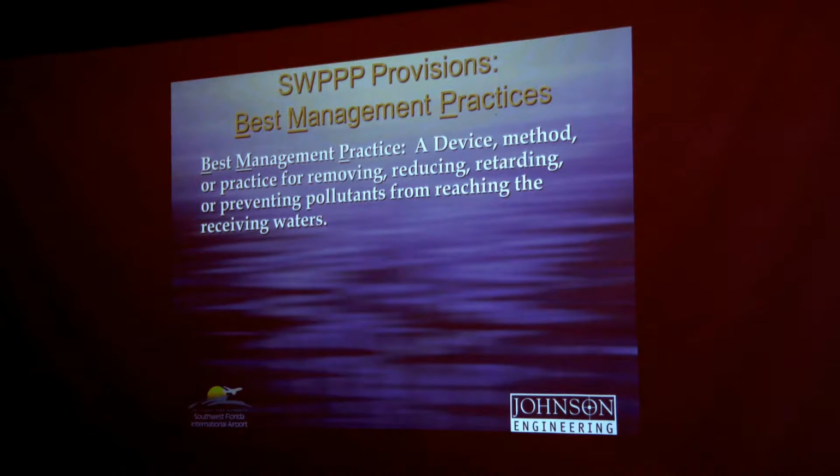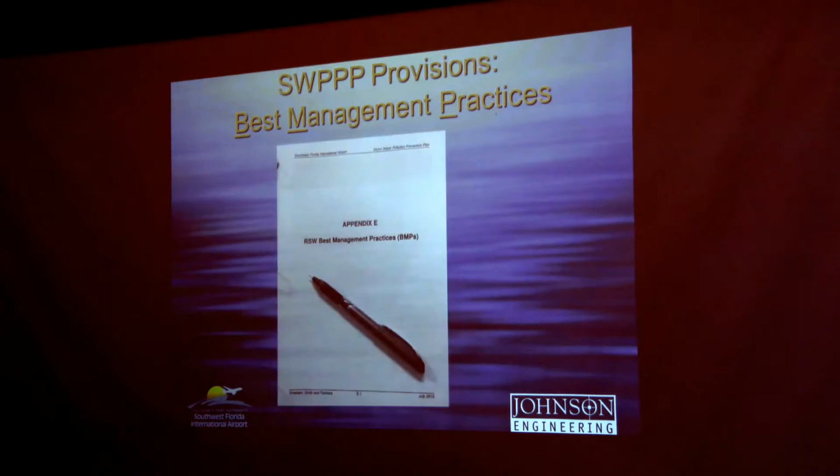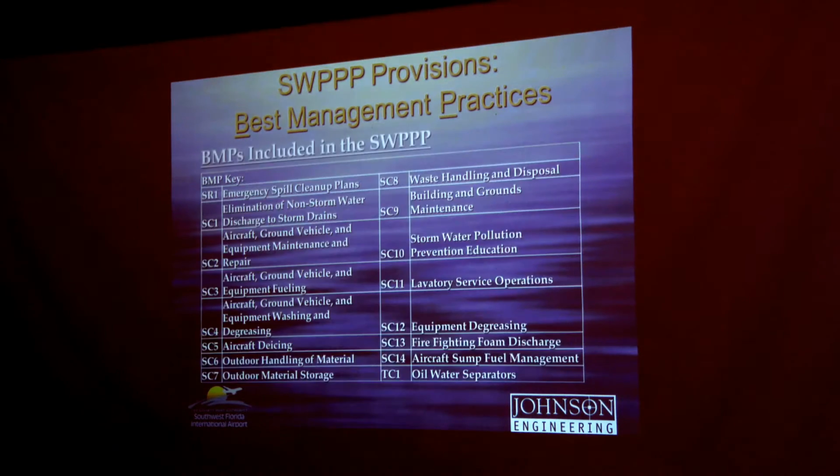Controls are also known as best management practices. A best management practice is a device, a method, practice for removing, reducing, retarding, or preventing pollutants from reaching the receiving waters. And we find these best management practices stashed away in Appendix E of the SWIP. These BMPs, again, are organized by activity type. These are the areas and activities where BMPs have been developed.